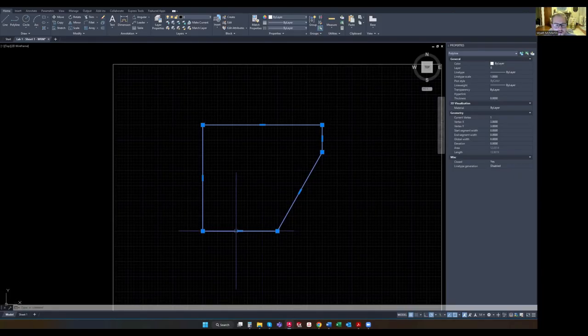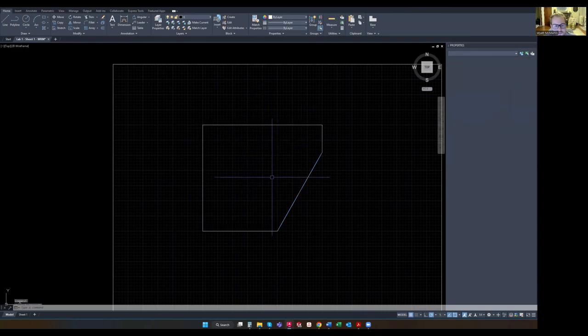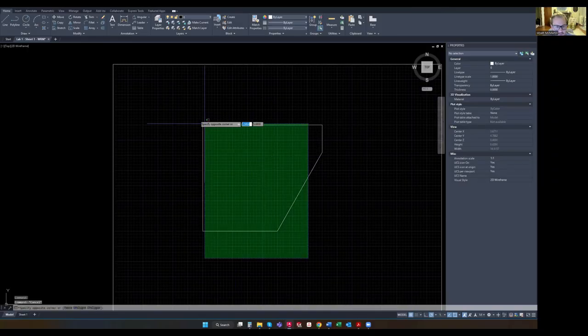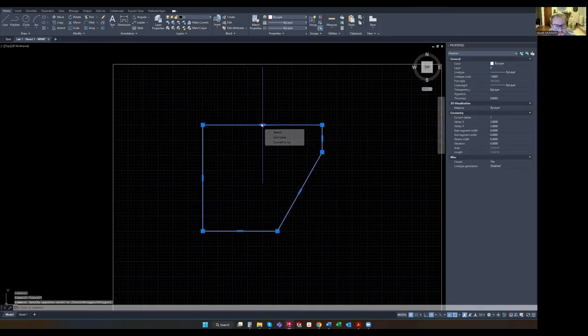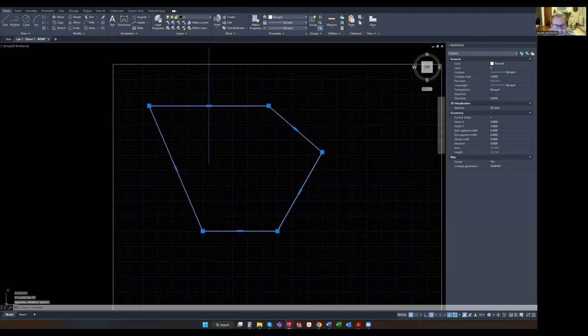But polylines in AutoCAD are really nice to work with because it gives you these pick points at endpoints, and then it gives you these midpoint pulls that allow you to manipulate the shape a little bit. So you don't have to do this on yours, but I'm just going to show you. If we just click that middle pull, we can click and drag that in any direction.